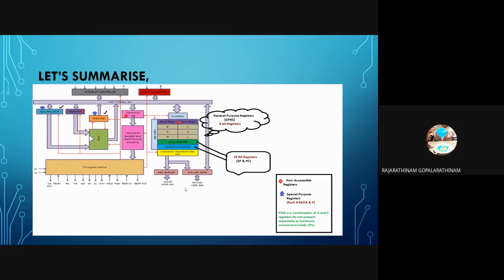If I have to access the memory, then the program counter has to point to that address, right? Then only I can access the memory. So I have to fetch all the 3 bytes. Then my program counter points to the next instruction. Then the next instruction's opcode will be fetched, right? If you go step by step, byte by byte, then it is always 1 byte at a time, right?